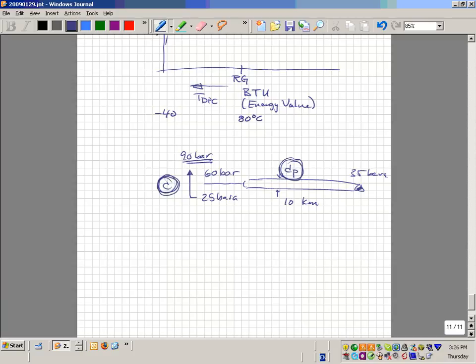And they design, so there is kind of a trade-off. You raise the pressure in the pipe, you have to compress more, you have more back pressure, but then you can have bigger fluctuation before you have to start to switch on compressor and start to switch on more wells. And in fact, there were 2 PhDs just recently, financed by GASCO, which is the Norwegian gas export system, looking into the optimization between high pressure, how much you gain due to fluctuation, you don't even feel them on the upstream side. And if you go with low pressure, much less to compress. But then each time on the other side they have fluctuation, and then everyone has to put in extra compressor. Very, very interesting issue. Okay.